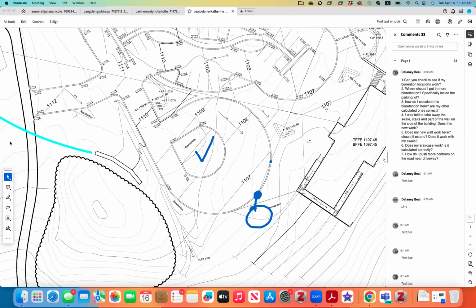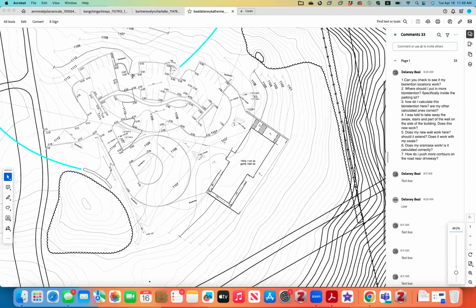I would stop my pavement somewhere here, because people won't stand over there. There's no room to get up from there. So this is where your water should come out to a retention. Where would the curb cut be? The curb cut should be there. All right, so those are the places you need to have retention.